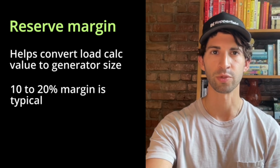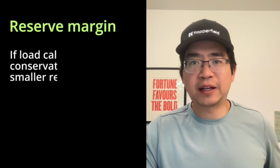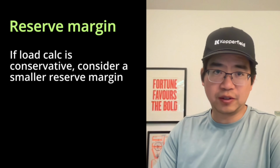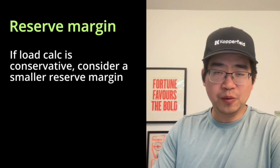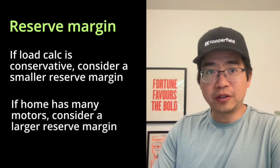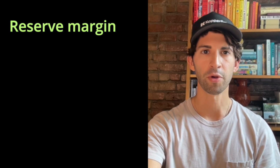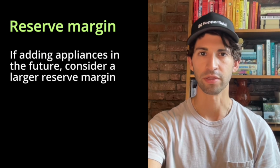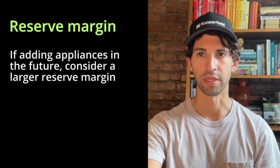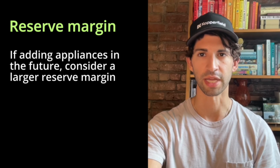A margin of 10 to 20% is typical to account for general growth and safety, but you may want to adjust it based on the needs of your customer. For example, if you feel that the load calc is conservative, as it might be for larger homes due to the fixed 3 volt amps per square foot lighting load, you might choose a smaller margin. On the other hand, homes with a lot of motors may need a larger margin. Motors draw significantly more power at startup, and you'll want to be sure you're covering those startup surges. If the homeowner plans to add more appliances in the future, that's another reason to use a larger margin. This home has a relatively normal amount of electrical load. For homes with EV chargers or other large loads, consider load shedding or load management to avoid oversizing the generator.